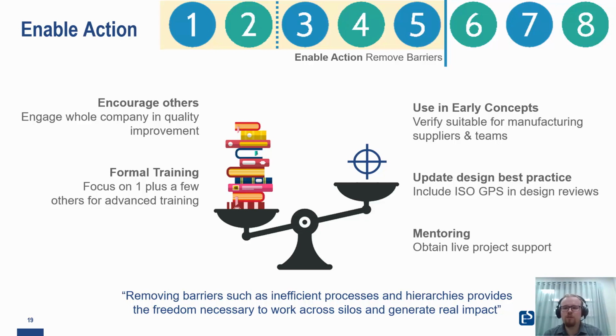This can often be done by implementing ISO GPS with PLM using model-based definition by specifying our dimensions on the geometry rather than on drawings. And it often goes hand in hand with digitalization and single source of the truth programs, where we want to utilize our geometry and model-based definition to ensure that our parts and our assemblies are fully specified on the geometry, and drawings are either supplementary or not used at all.